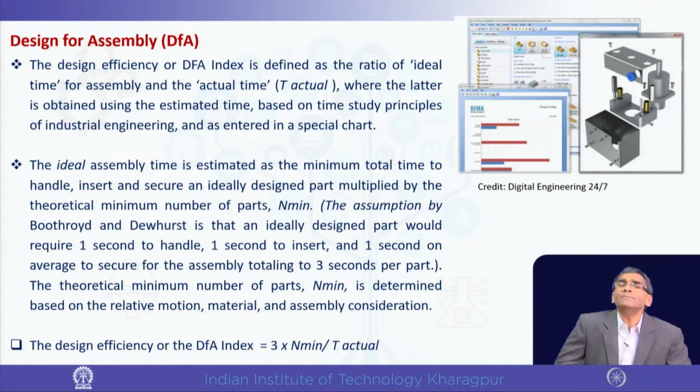Now, ideal means what? Ideal means, say if you are putting a square peg in a square hole, one has to locate where the square edge is, and position etc. But if this pin is cylindrical, then that requirement is not there, but still positioning is necessary at the hole, which should take less time in assembly.